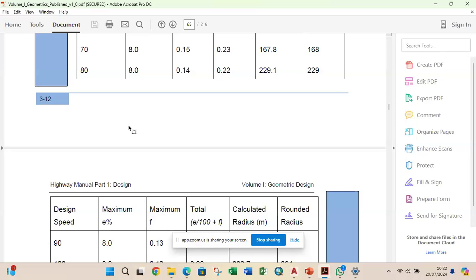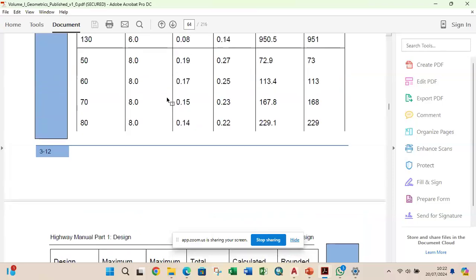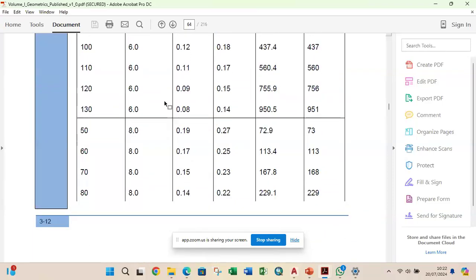I think for state road and rural road, you can use 60 kilometers per hour. Then for our normal estate roads and all, you can go below, 15, 20, 30 kilometers per hour for design speed. So that design speed is being controlled by the super elevation assigned on that road. For federal roads now, the maximum super elevation prescribed here in the manual is 8%.